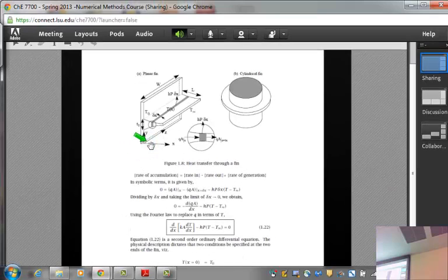So what you do is you recognize that in such a case, the temperature close to the base is going to be different from the tip of the fin. So it is a distributed model. There is significant spatial variation. We cannot avoid that. But I can say that this fin is operating under steady state condition. Then I will get a steady state model. Then I can ask what happens if I'm just starting it up. Then I have to include the dynamic one.